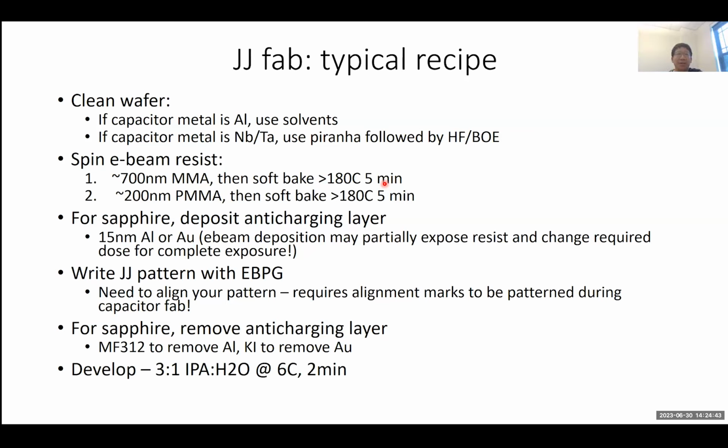Okay, so a question on aging. What are your typical aging parameters? How much does the resistance increase in the first few weeks? And also, do you see qubit coherence time change when the junction ages?